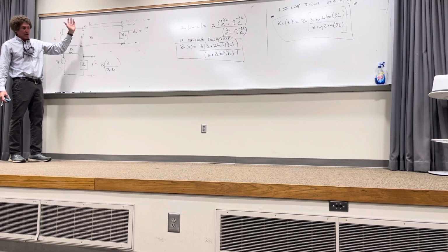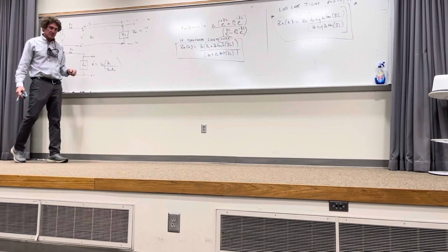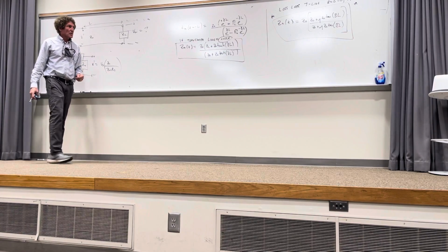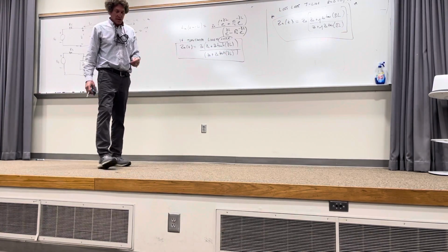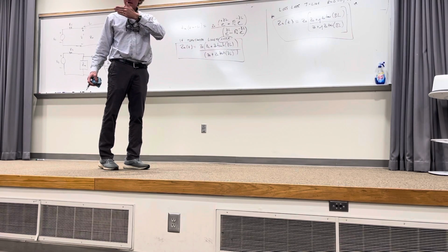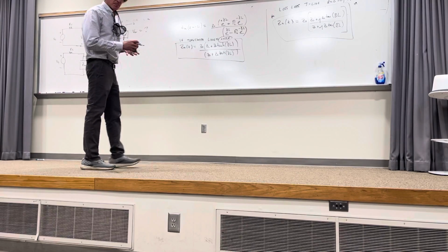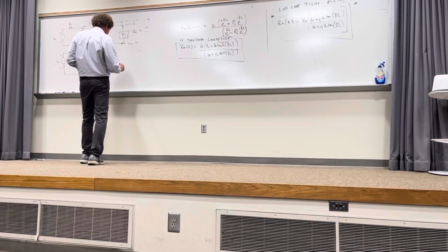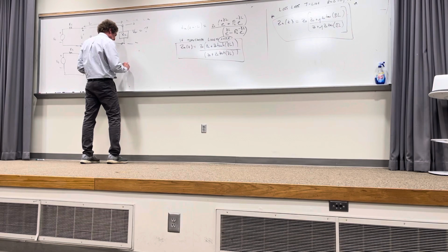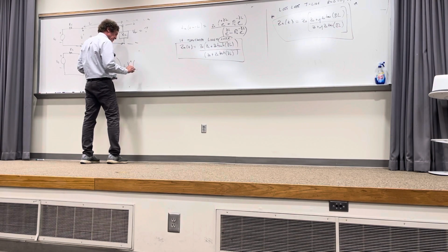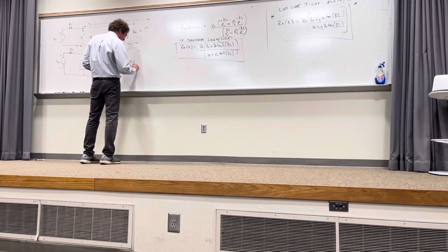Okay. Now, I've got that. What is this equal to? Think back to the equation, I've erased it, of voltage on the line. There's a propagating wave going in the positive direction and a reflected wave in the negative, right? So right here, what this is equal to is V0 plus, and it's equal to E.